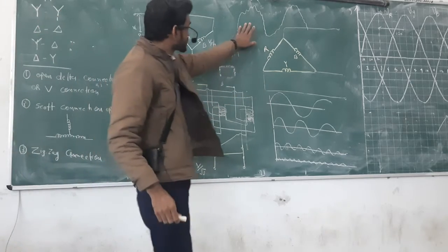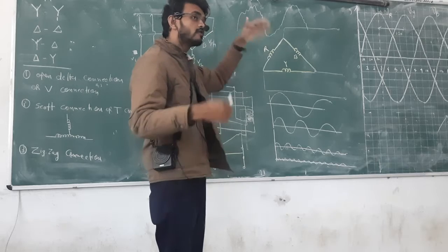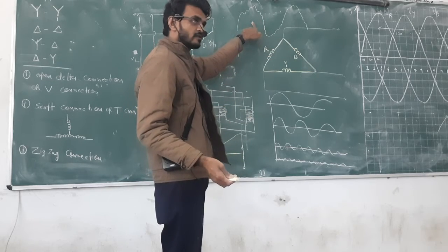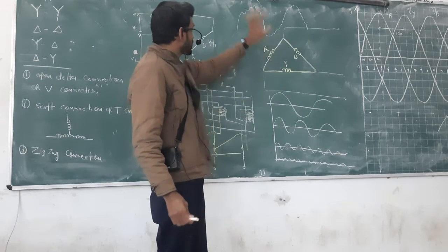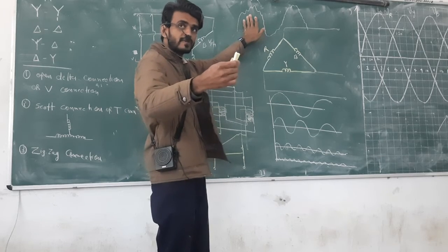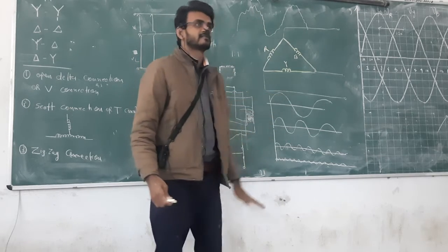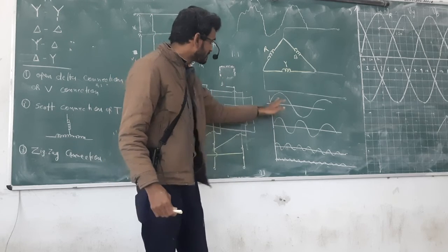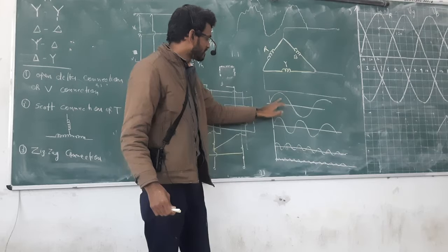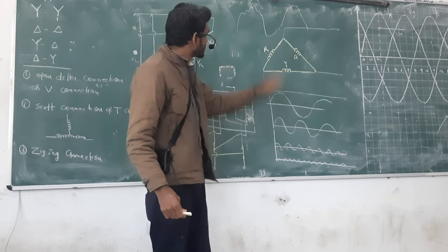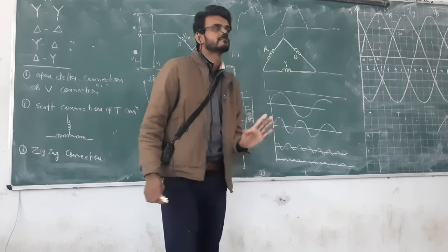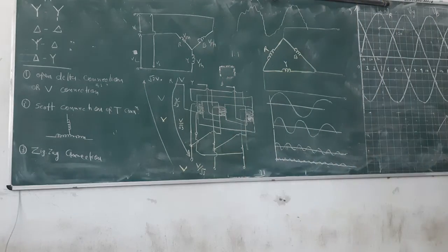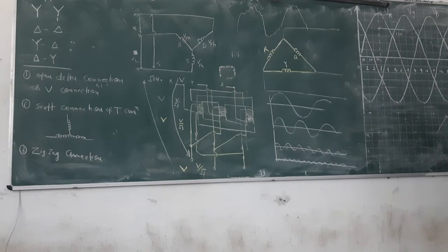If you have a given waveform, you can extract what is hidden inside it. If you have the waveform and apply the same mathematics in reverse, you can get all the separate components. The main component here is called the fundamental component. It is nearly equal to this wave, and the other things are the distortion, which we call harmonics.